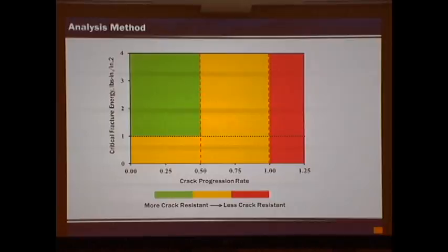So what does that mean? I think that's the next question. Now we can define that out. The next step we wanted to take was to look at what it looks like from a coefficient of variation when we do the analysis, and whether it still differentiates between good and bad mixes. When we did the new analysis method, we were seeing coefficient of variation below 20%, which we were very happy with. A lot of them are now even lower than that with the improved gluing method.